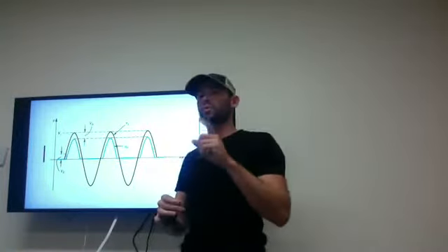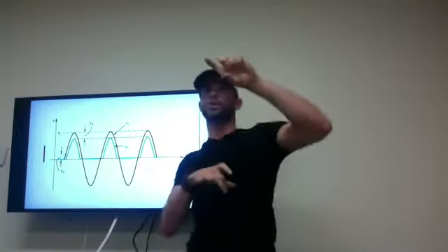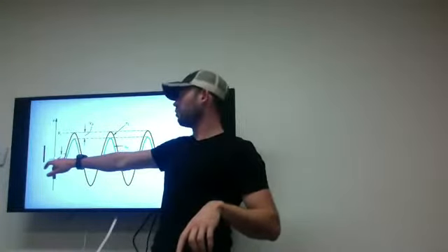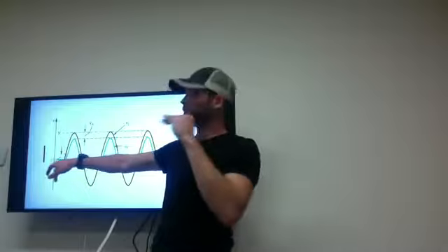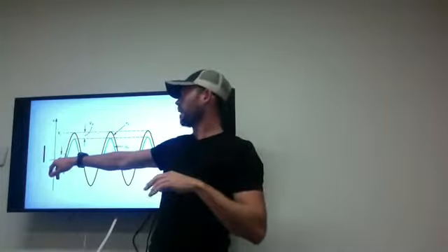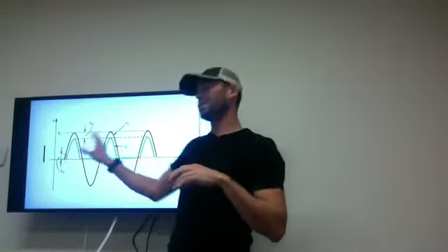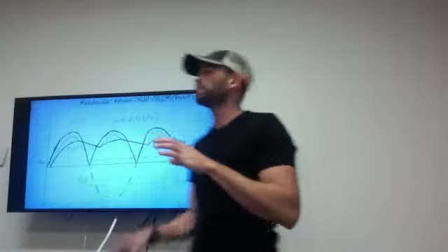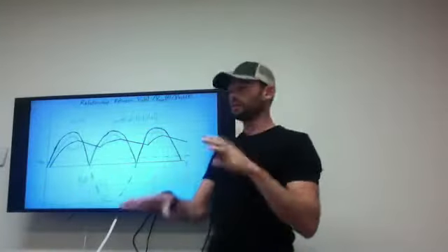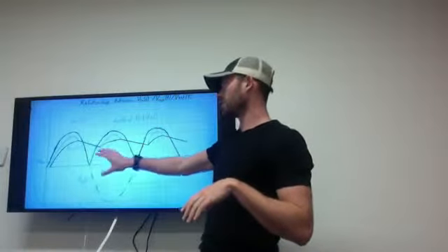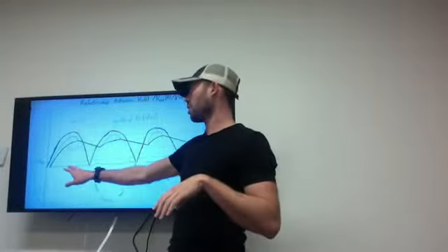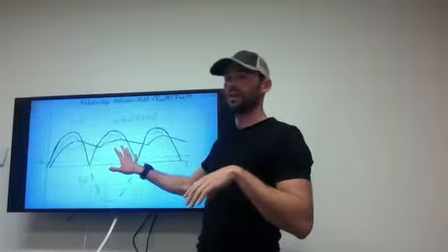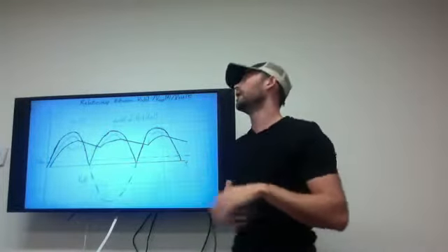In our bridge rectifier, each section has 2 diodes, so this gap is 2 VD, two voltage drops over the diode, and this follows all the way through. What happens in our case is a full wave, so when we flip this up, it not only takes this part, but it also takes the voltage across the negative portion.